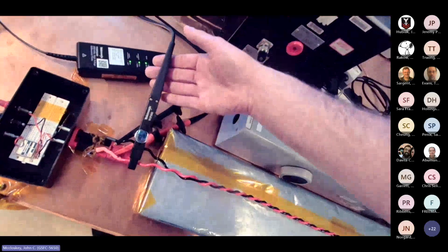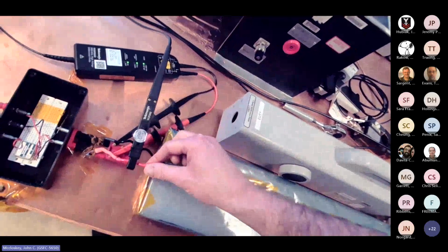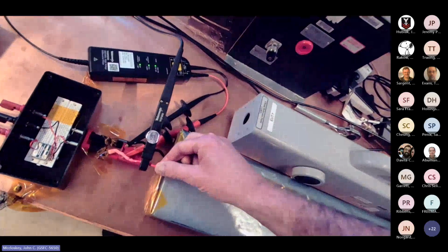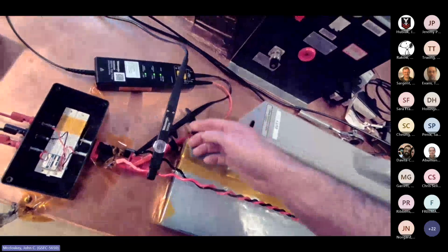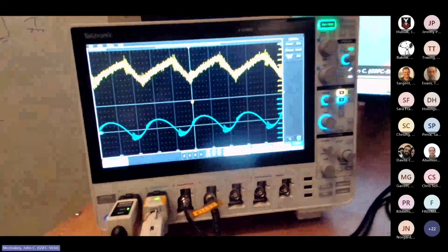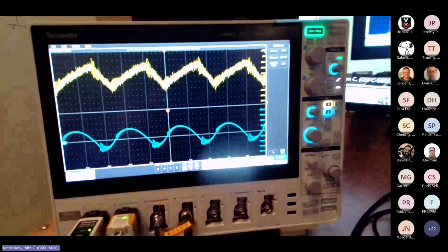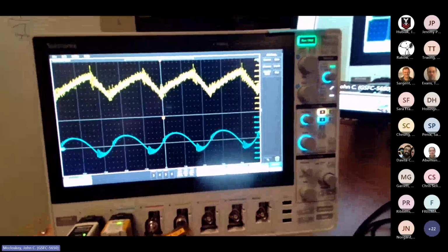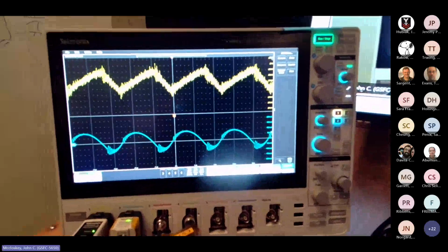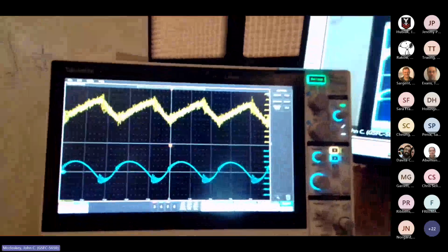And then this is just a basic scope current probe on the power feed to our power converter. So the two traces we're looking at are voltage and current into the converter. The yellow trace, the top trace, is voltage, and the bottom trace is the current. That voltage trace is centered right around 28 volts. Another little test and measurement tidbit I like to pass along.